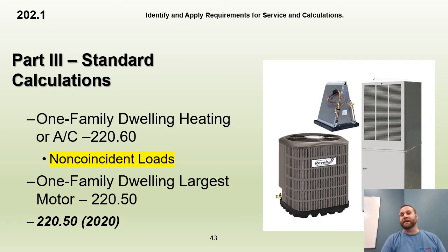If our heat and our AC are running at the same time, then one of two things is going on. We probably have a heat pump and we're not even allowed to consider this for the heat pump, or something's really gone wrong with the wiring and the heat is calling for AC at the same time as it's calling for heat, and something's really messed up there. So that being said, those two loads never run at the same time.